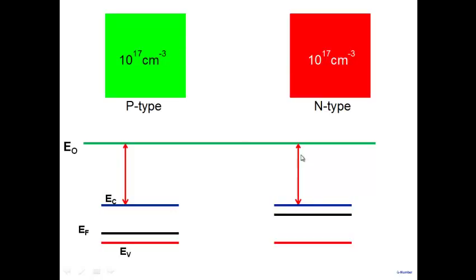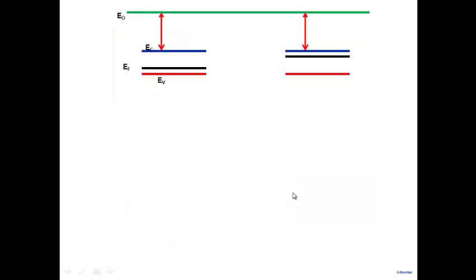So what will happen to E0 here? It will start to go down. Remember, as things get positively charged, in terms of energy, it starts coming down. So E0 here will start coming down. Eventually, this EF will line up with this. So let's do that. Energy band diagram in equilibrium. What is the starting point? EF is constant throughout. So draw in EF constant throughout.